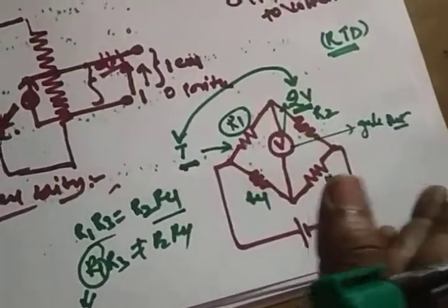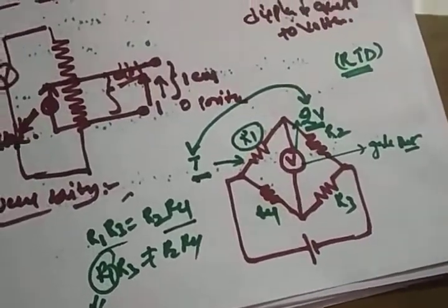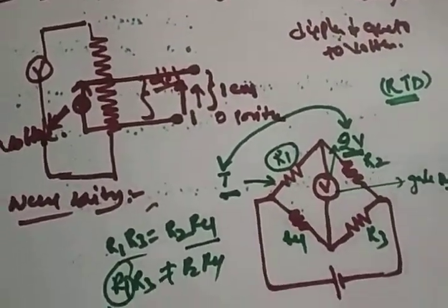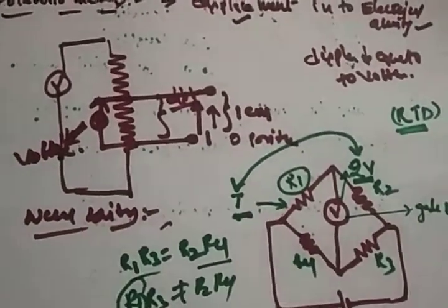That is what we discussed in strain gauge. In the concept of strain gauge, LVDT is a linear displacement which is converted to voltage. There are different transducers present in daily life, but we don't need to go through all the transducers. We just need to know what a resistive transducer is and how displacement, resistivity and cross-sectional area are converted to changing resistance. If the resistance changes, definitely that can be converted to voltage itself. So these are about resistive transducers.